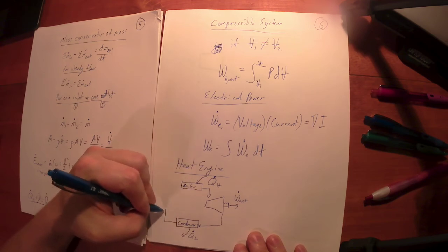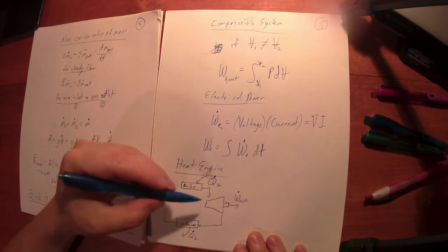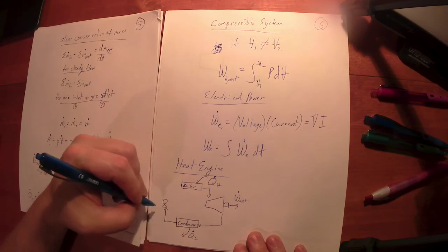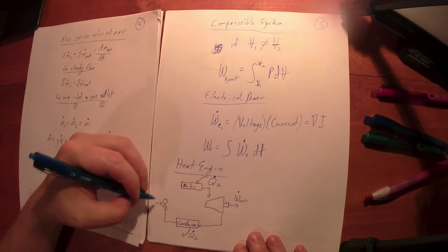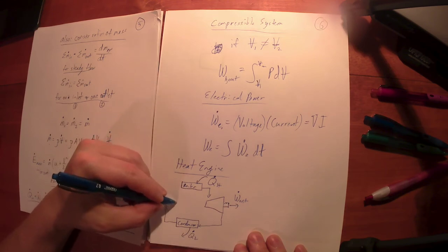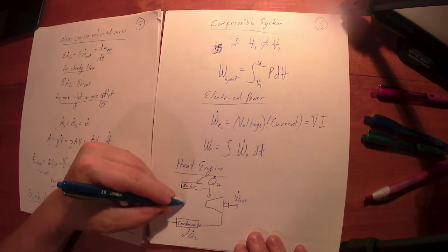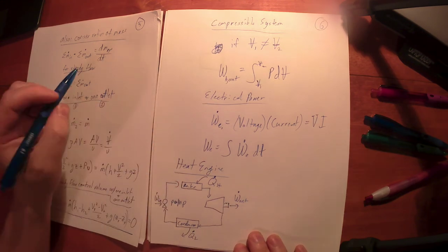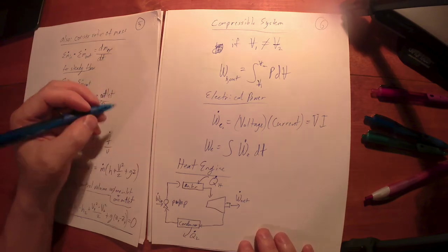And then somehow we've got to increase the pressure because I want high pressure here. Normally how we increase the pressure is we get it down to a liquid form in the condenser. We put just a little bit of power input to a pump. That pump supplies a boiler and the cycle repeats.